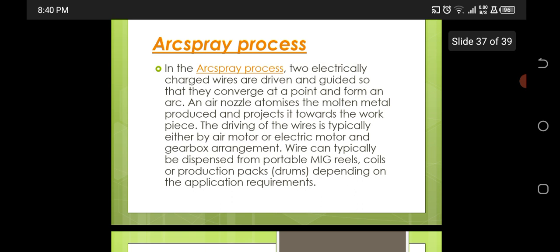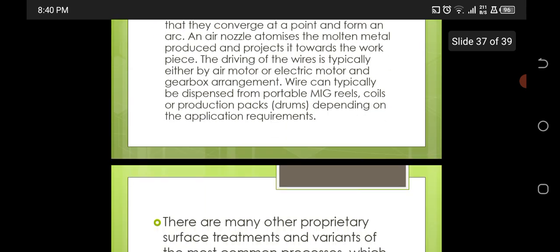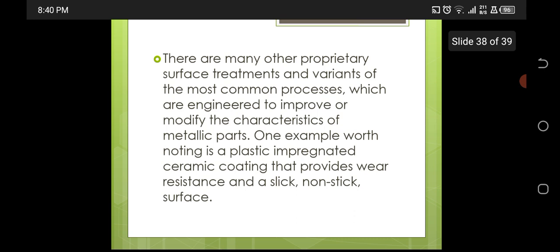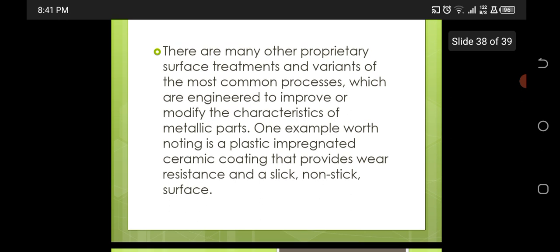As we have seen in these processes, the main thing is the melting of the coating material, and then the air passes through, so that air leads the melted material toward the target, and after reaching the target it binds with the target easily, and when they bind they will act as a protective coating, and it prevents corrosion. And because these are thermal methods, this involves heat.